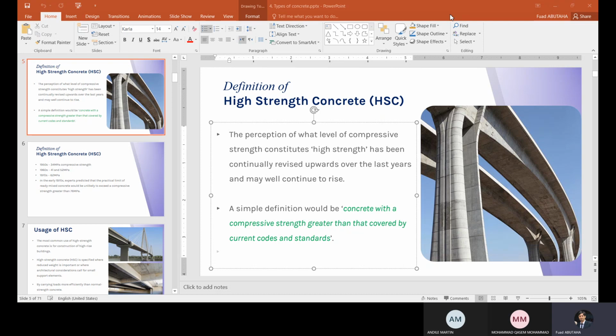Okay, if I use the same water content for both of them, mix one has a water cement ratio of 0.4, and the second one also 0.4. I maintain the water contents. Then I need to observe the effect of the particle size itself on the workability. One has a maximum size of 14, and the other has a maximum size of 20. Which of them will give higher or lower workability? Only the effect of the particle size.